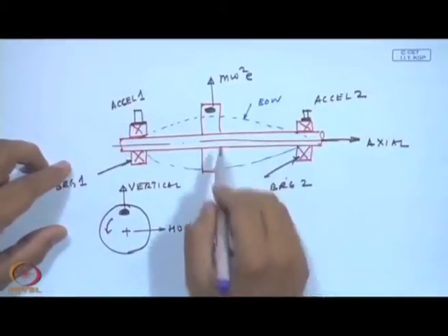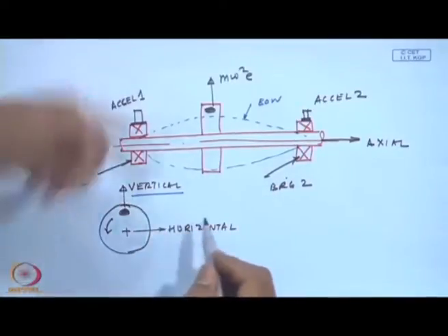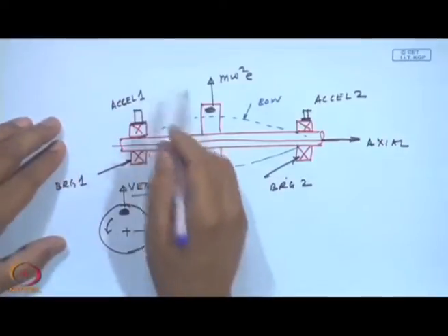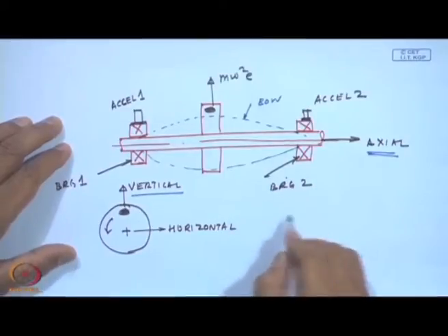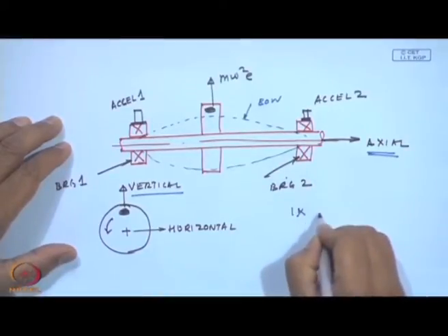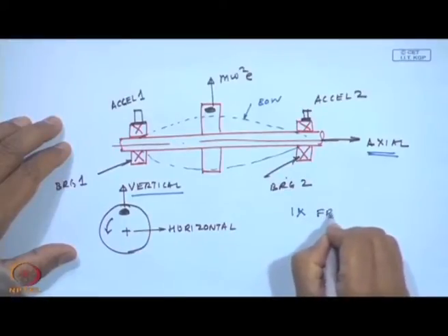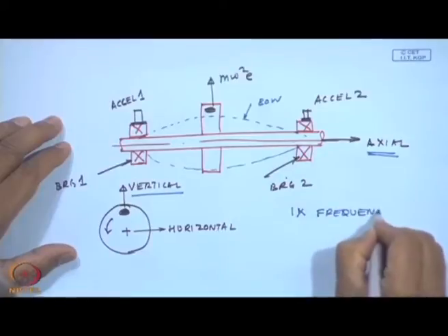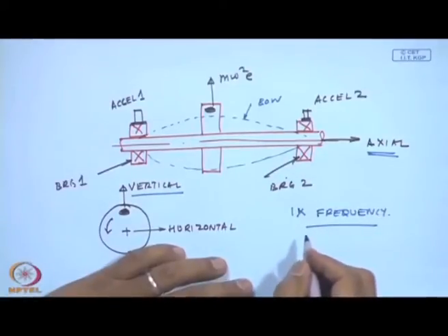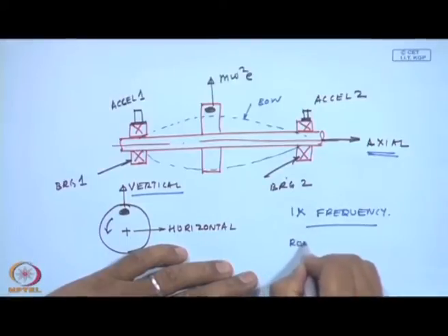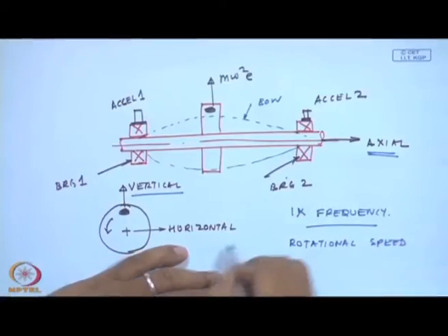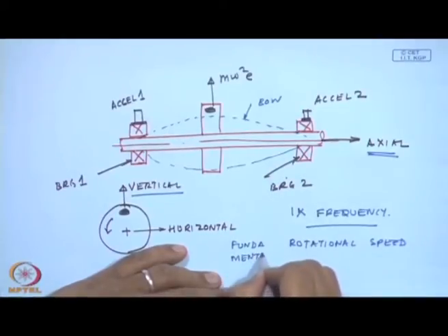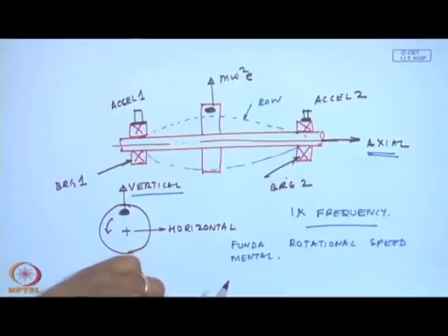Okay. They will be in the vertical or horizontal direction. These accelerations will be much higher than the axial, and they will be at the 1x frequency. By 1x frequency, I mean it is at the fundamental rotational speed.